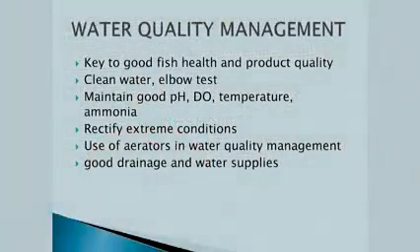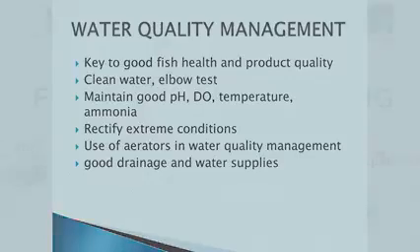You can either add more water to the pond. You place your inlet pipe about 1 meter above the pond level, and you allow the water to splash into the pond. At that time, it will be creating bubbles. Hence, it will be adding more dissolved oxygen to the pond.